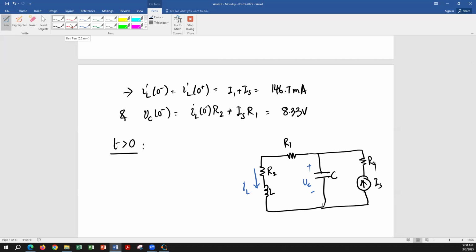What do we do first thing when we are analyzing RLC circuits for forced response? Fine. Good. Okay, now what type of circuit do we have? Parallel or series? Natural circuit, that is. We have a series circuit, natural, because of course for the natural circuit you have to remove the current source, and when you eliminate the current source, it's going to become open. So R4 is going to be gone. That means you will be left with a series circuit. So the natural circuit is the series RLC circuit.